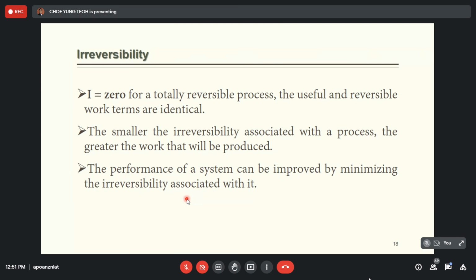From that, I can check the temperature and pressure and what the corresponding entropy is at that condition. From there, I can estimate how much possible loss there is during the conversion or heat transfer based on the amount of entropy in the system. Entropy can be increased or decreased. If you increase the entropy, it means that you decrease the total possible work output.